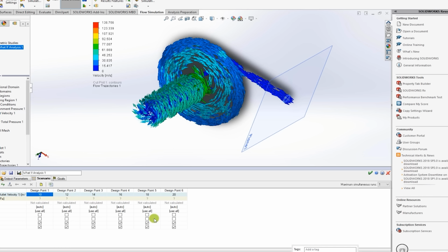Now all of these cases are going to be running till 500 iterations. So that's the best part. So what I can do is I can just hit submit, and since this is a project, I won't be discussing the results that I get, but when you run this, you will be getting the velocities at the outflow, and the total pressure at the outlet as a function of the velocity. So you can use both these data sets to create a pressure versus flow rate plot, and that is going to be the result that I'm expecting from your project.